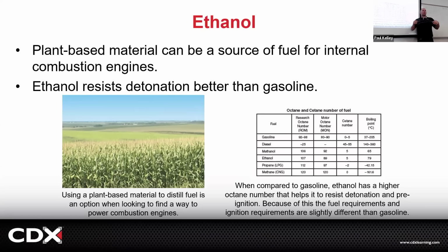Or any mix. So if you go to Costco and you pump up top tier fuel 87, you just fill it halfway. Then you go down the road to Shell and they have ethanol, you can put E85 in there. Now you have a mix. It's not quite 50-50, but let's say it's like 47% gas and 53% ethanol. The flex fuel sensor will pick that up. The computer will adjust all the timing, the fuel trim. It'll adjust everything, knowing you have a mix.